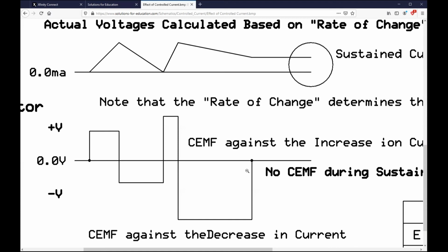You wonder, whoa, what's going on? If you put paper in there instead of plastic, it really makes a difference what kind of paper you have, because paper is really quite fibrous if you look at it under a microscope. So yes, you're right. That's what makes them blow up. That's why they blow up if you happen to reverse charge them, is because it is no longer a capacitor. It is a resistor with liquid, and that liquid overheats, and away it goes.